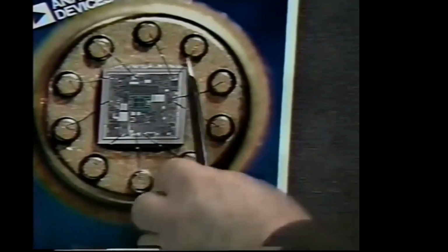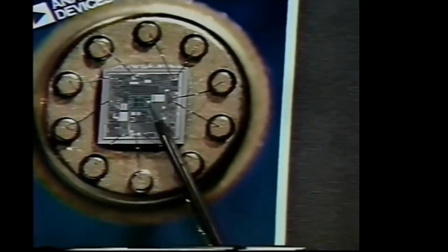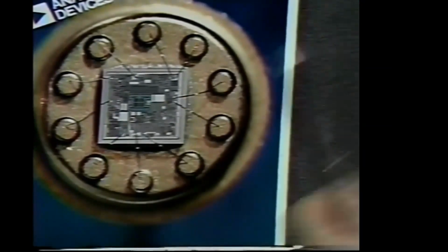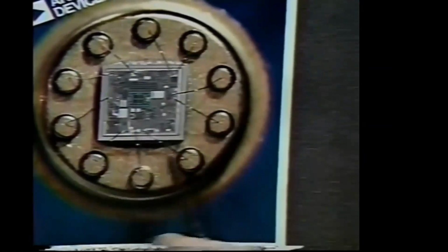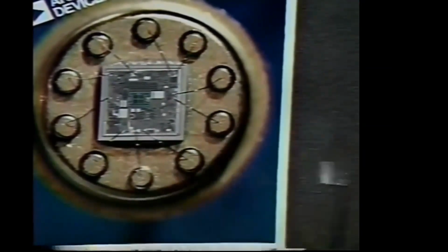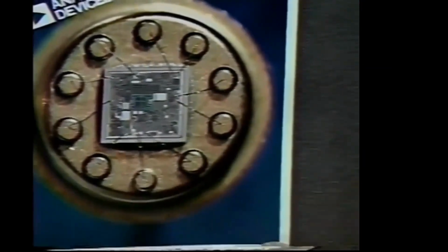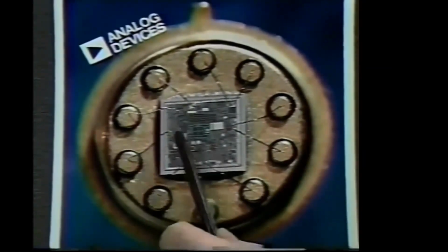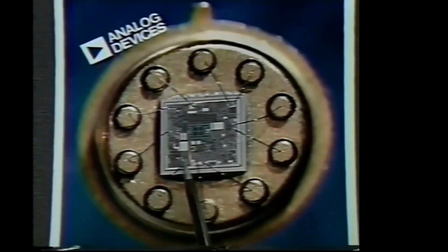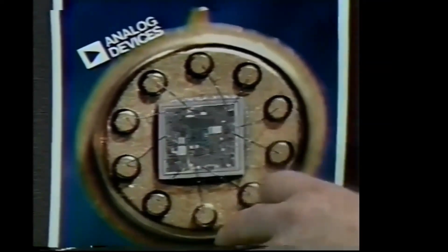The system was realized again in 1991 and is shown here in the original package in which it was sold. Again, it's a complete monolithic chip. At the very center, you can see the exposed sensor, which I'll show you ever closer-up pictures of as we go on. It's in a 10-pin package, again, to accommodate the gain requirements of the variety of users. And it has something which you may or may not be able to see. It has trimmable thin film resistors. This whole chip can be calibrated at the wafer level.